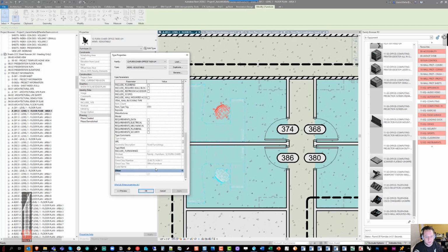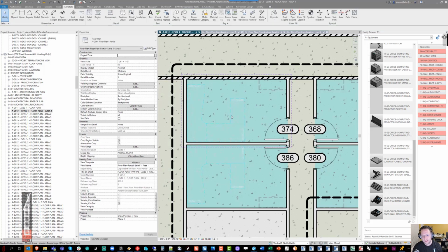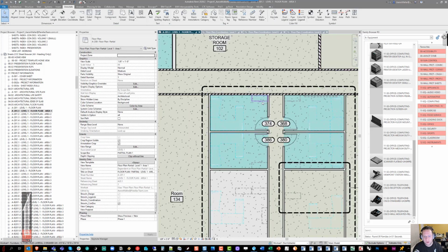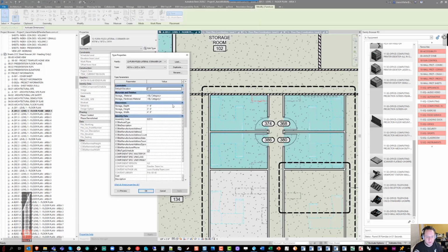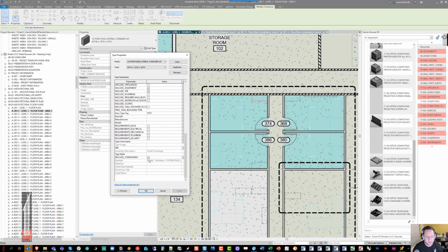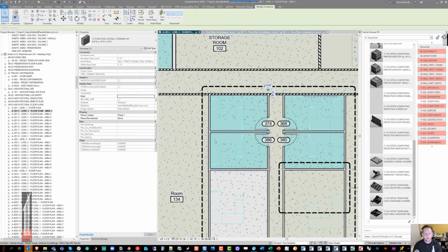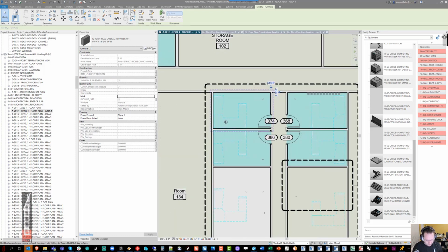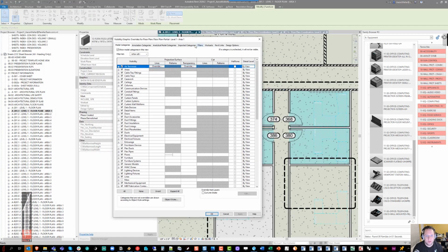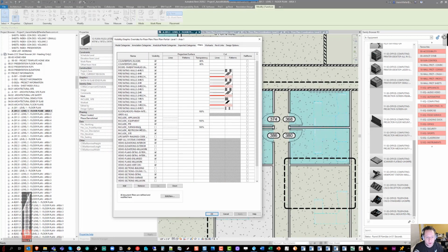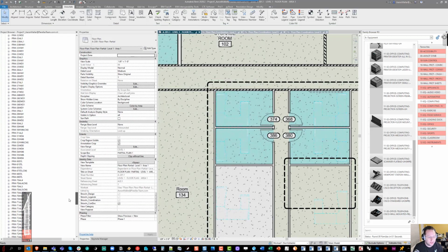If we then start going through the rest of our furnishings and checking the include furnishings box, as we said before, we are now adding them to the furnishing schedule, but also taking them out of the views anywhere furnishings are unchecked. The includes parameters are also the same ones that are driving the poche on the furnishings plan.